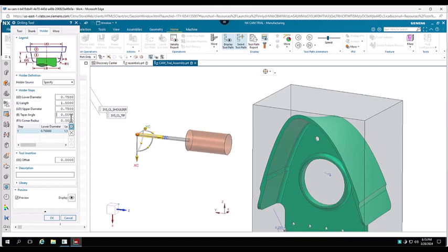I'm just going to do a generic collet holder here. So then we'll throw a corner radius of 30 thou or so. You'll see that added to the bottom here. Now I need to add another set here, so I'm going to hit the plus button. You'll see it's added the exact same information that I had on 1 is now going to be on 2. It's stacked it on top of it.